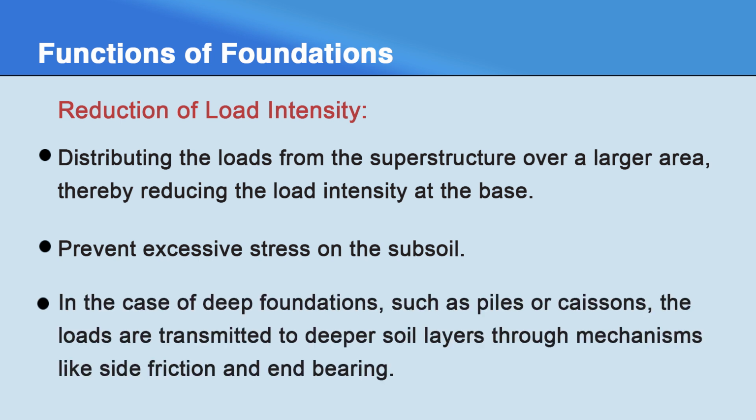In the case of deep foundations, such as piles or caissons, the loads are transmitted to the deeper subsoil layer through mechanisms like side friction and end bearing. By spreading the load over a larger area, foundations can help to ensure that the underlying soil can support the structure without experiencing excessive settlement or failure.